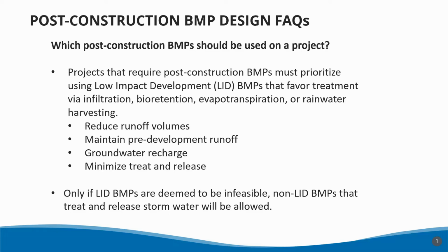And as much as possible, we would like to minimize BMPs that treat and release stormwater, such as detention basins. In a detention basin, as it stores water, as 1 gallon of water comes in, 1 gallon of water comes out. So we definitely want to promote BMPs that actually store and treat the stormwater.